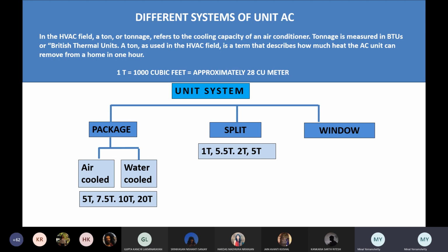So then what you have to do in a split unit is take out the condenser and the compressor, because one is heat producing, one is sound producing, and keep them outside. Okay. What you need inside the room is the evaporator with a small fan, and today we get fans which are of a silent kind. So you put a fan there, and that's how you start getting cool air within the room, without the noise and without the humming sound that comes from the compressor. So this is how the split works.